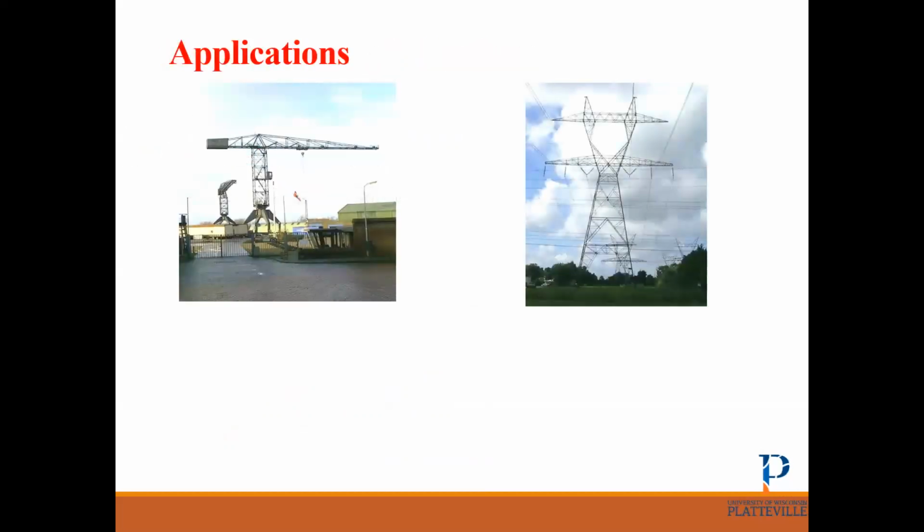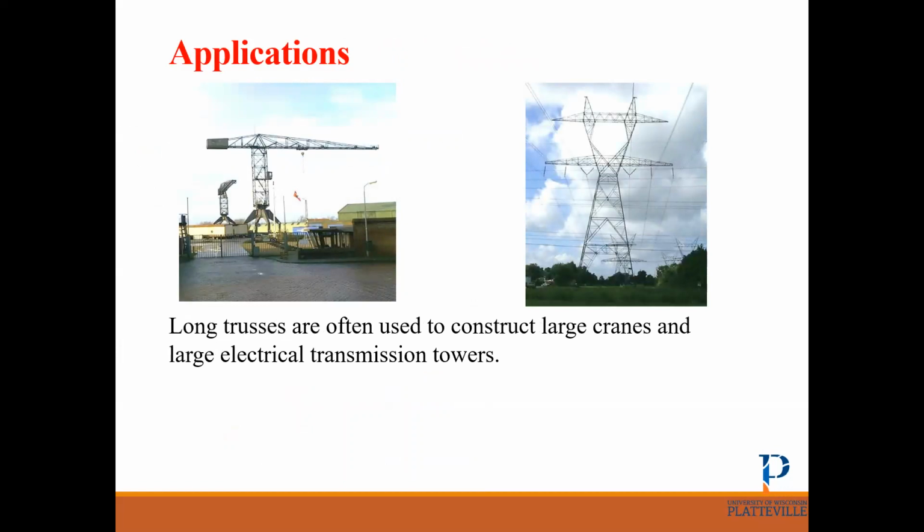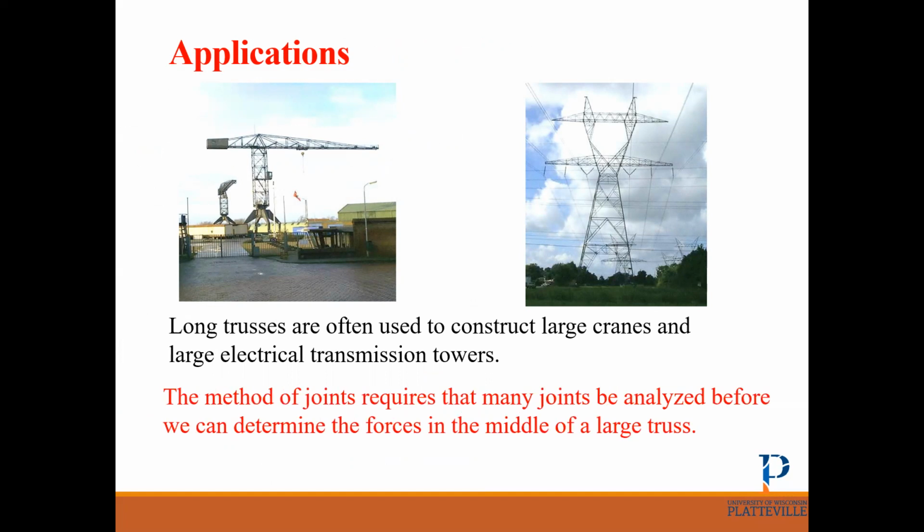Okay, let's see two applications of trusses. You are familiar with line trusses used for construction, or electrical transmission towers, right? If you just want to analyze all the joints, it's very hard, especially in this electrical transmission tower. It's very hard to find all the joint internal forces. That's why we use method of section to determine the internal forces in these trusses.